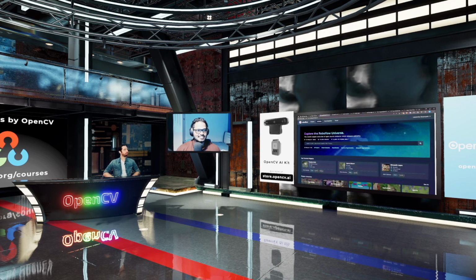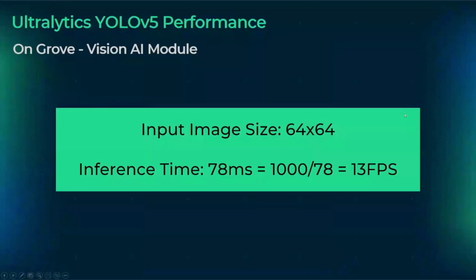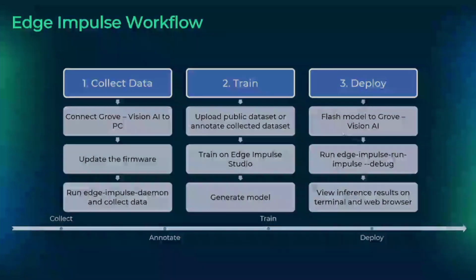Exactly. And for the Ultralytics YOLO V5, this is the performance from our testing. On the Grove Vision AI, we get an inference time of about 78 milliseconds, which is about 13 frames per second. This is actually trained on an input image of 64 by 64. I mean, 13 is fine to have decent object detection work. But later I will show you how this can be achieved better with FOMO. So just stick around for a couple of minutes.